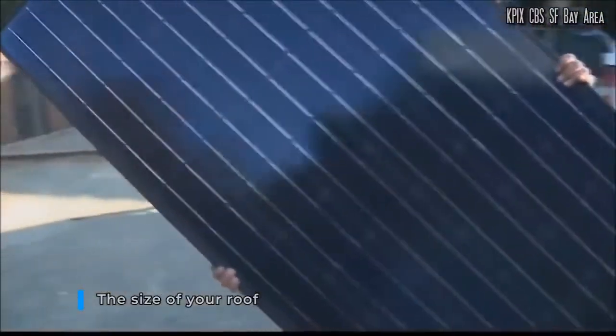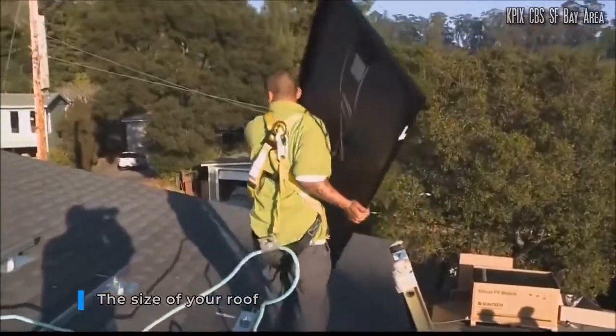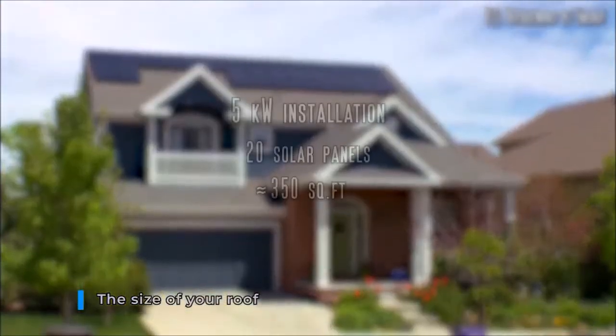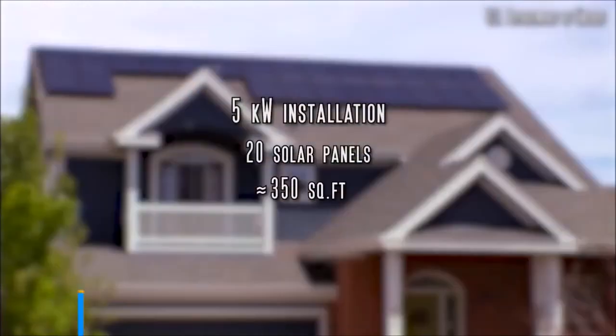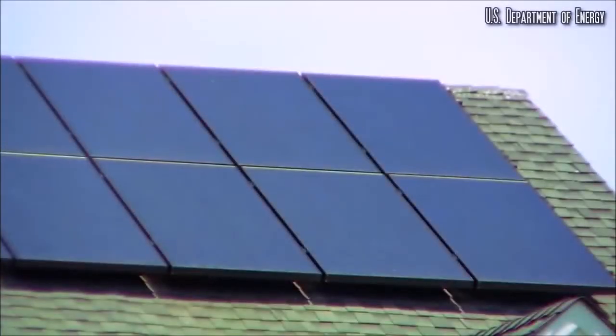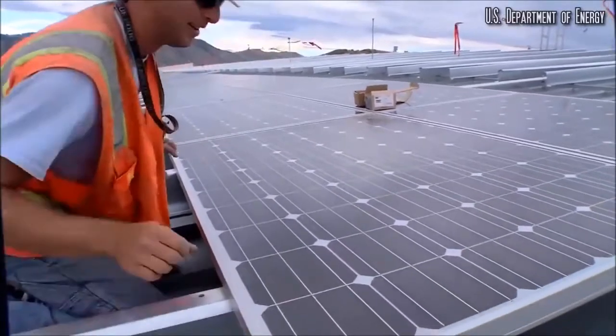The available surface on your roof, the unshaded part with the appropriate orientation, determines how many solar panels you can install and consequently your savings. A simple case to have in mind is that you need roughly 350 square feet in order to install 20 solar panels, which would have a total power of 5 kilowatts.